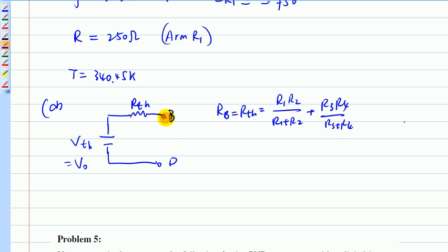Now we connect the voltmeter over here, which means I will have this Rin, the internal resistance of the voltmeter, here, and you're looking for the voltage across here. If this is infinite, then that's basically what you're looking at. But if this is not infinite, you will have a slight difference from VO. So right now this is your measured value, or you call that VO measured.